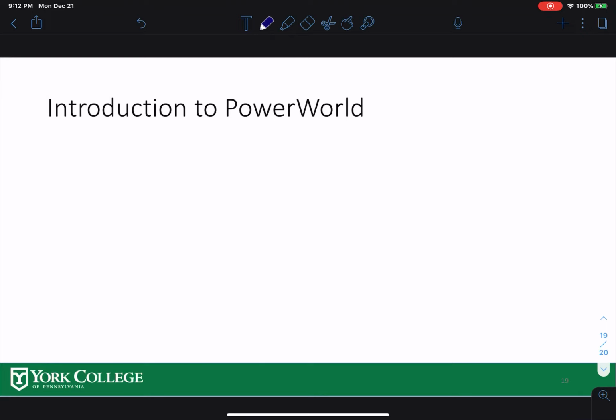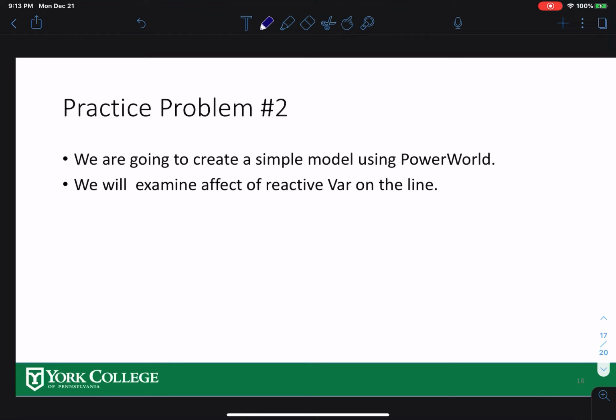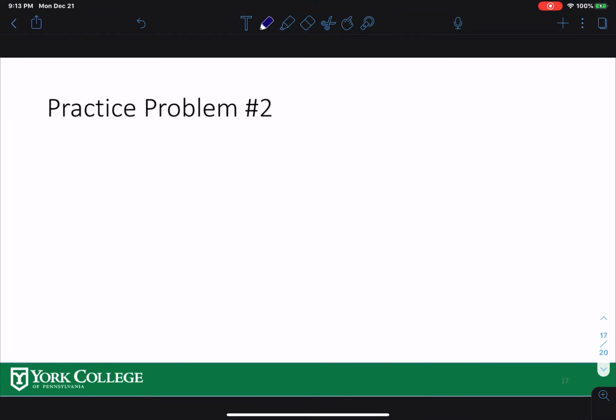We're going to talk about Powerwall in the class a little bit. Here's the takeaway from this whole class: for power factor correction, your loads are inductive, so you need a capacitor in parallel with the load to minimize the angle between current and voltage. That's the power factor correction. How much capacitor you need depends on the inductive power that must be compensated with capacitive power. That, along with the line voltage, defines the capacitance value. We're going to do the problem in the class.